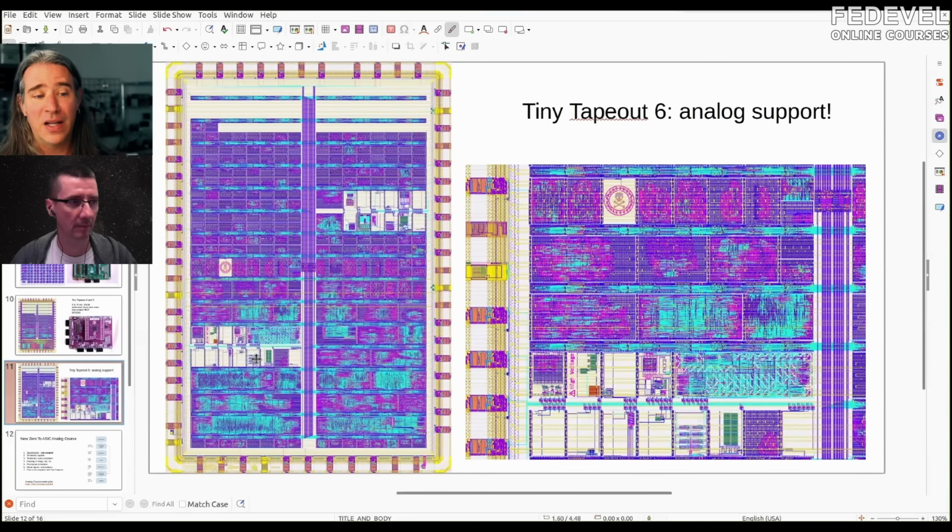Now, the reason this is possible now, the reason it wasn't possible before, is if you short out, let's say I short out ground and VCC, no one's project would be working. It would be terrible. But now the little squares are power gated. So if I enable my project and it's a short circuit, a straight short between power and ground, well, bad things will happen. But as long as it's not turned on, there's nothing.